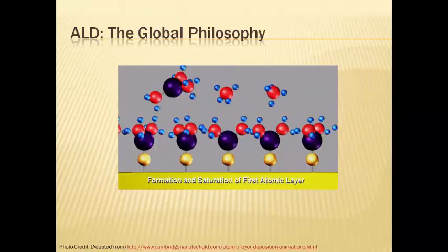Similar reactions continue to occur. It can be well understood that if there be N hydroxyl groups on the silicon surface, in presence of sufficient quantity of TMA molecules, N TMA molecules would react with them and would thus form a bed of dimethyl aluminium monoxide. And the reaction would stop thereafter. This is the self-limiting nature of the reaction, which helps gain a good control over the layer-by-layer deposition of materials with a thickness precision to its monomer level.